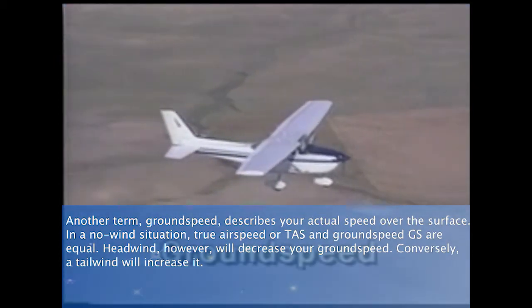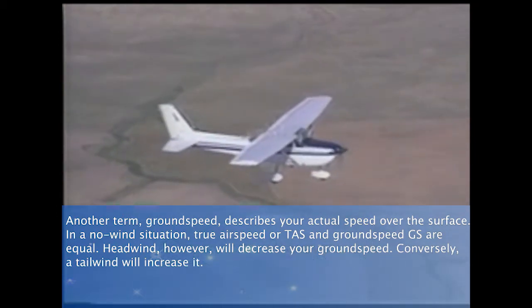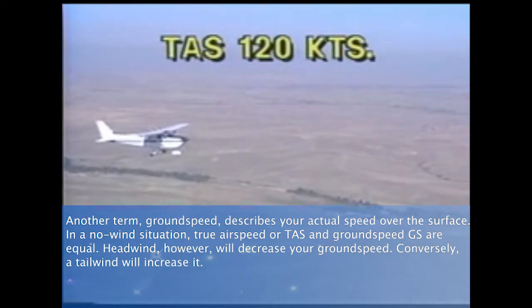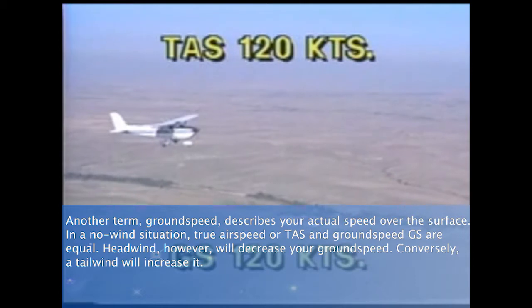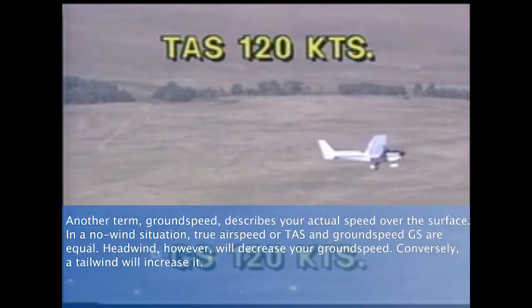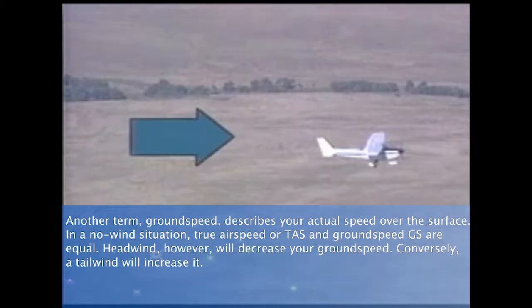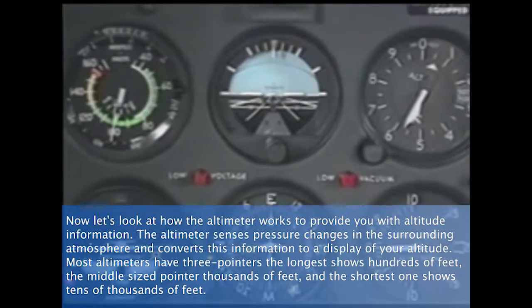Another term, ground speed, describes your actual speed over the surface. In a no-wind situation, true airspeed, or TAS, and ground speed, GS, are equal. A headwind, however, will decrease your ground speed. Conversely, a tailwind will increase it. Now let's look at how the altimeter works to provide you with altitude information.